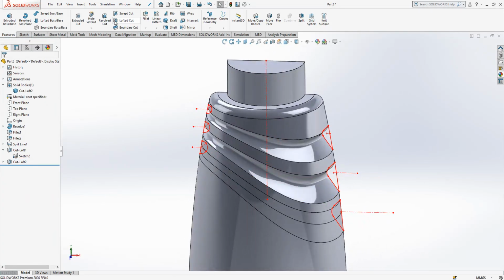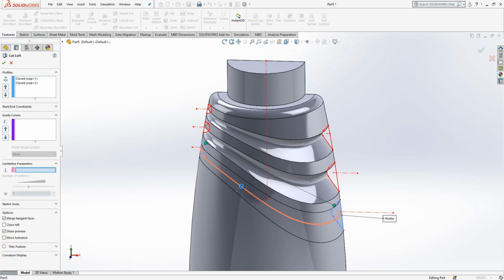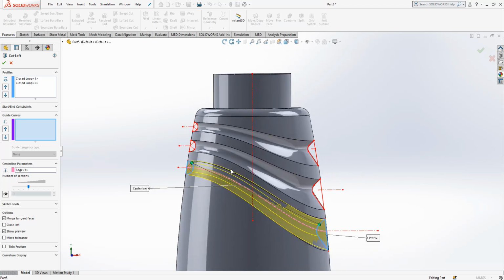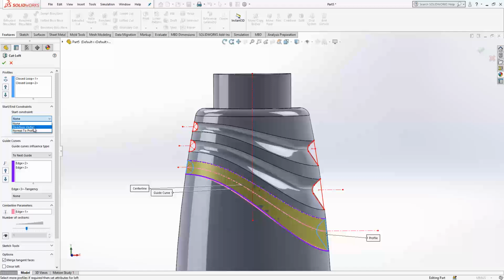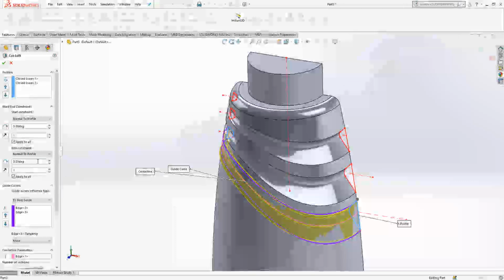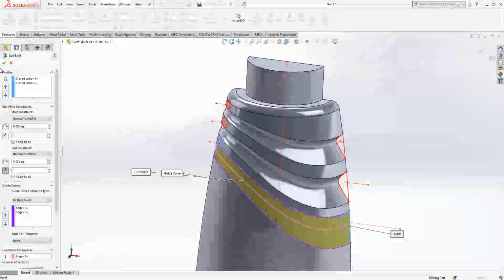Yes. Second also good. Third, select this guy, select this guy, and center line. Normally, if I did this in reality, maybe I would even define two other curves here. It's up to you. As I told you before, how many curves you have, that much control you have on the profile and on the generated cut, or let's say might also be an extrude. That is important.